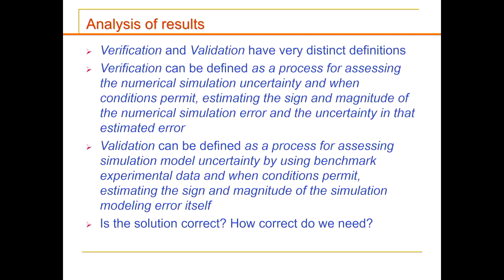My understanding of verification is to make sure that whatever settings you put for your problem, you assess, like, mesh convergence, a mesh independent solution, your meshing and so forth. So in terms of CFD, your verification is more on how you set up your problem, make sure you set up the proper boundary condition, assess it against different convergence criteria and so forth. Also test different numerical discretizations and so forth.